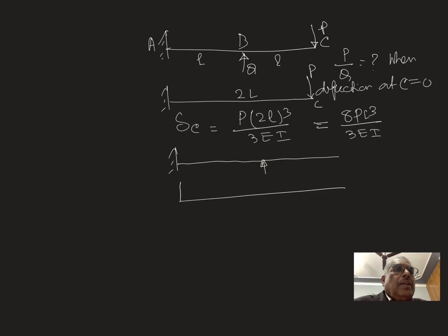The bending moment diagram will be QL, divided by EI, it becomes the conjugate beam. This is converted into elastic load, and this point is C, so this is C dash, and the free end becomes a fixed end. Therefore deflection at C in this case is nothing but the bending moment at C dash.